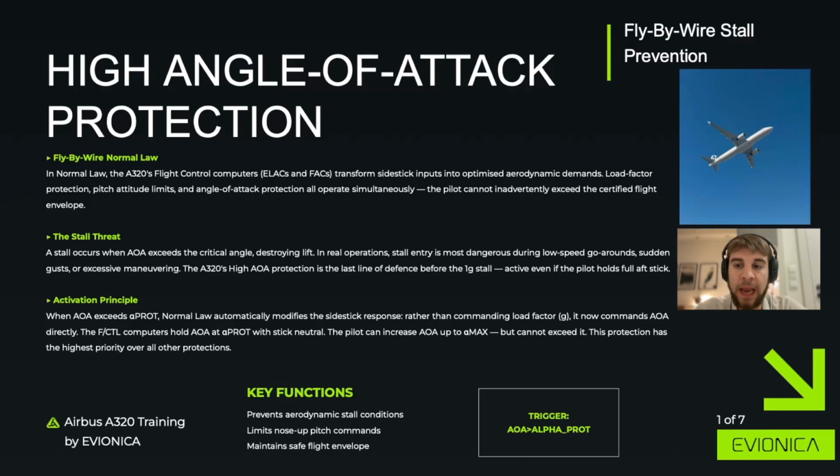In the Airbus A320, the fly-by-wire system operates under what is known as normal law. In this mode, the flight control computers interpret side-stick inputs and convert them into optimized aerodynamic commands. This means that multiple protections are active simultaneously, including load factor limits, pitch attitude limits, and angle of attack protection.